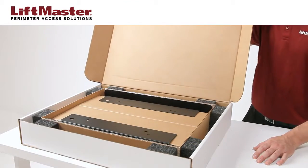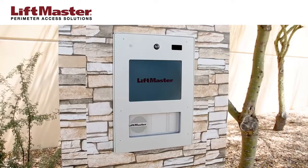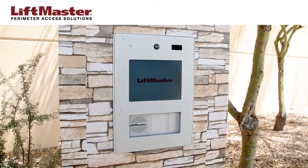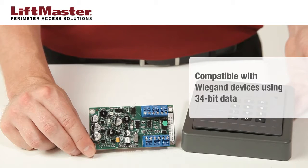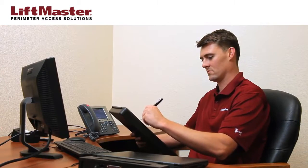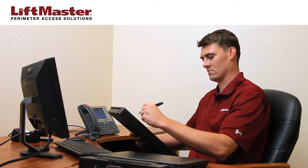If you are replacing an Icon 26 or Infinity L device, you will need to order the retrofit trim ring kit, IPAC RTR. The IPAC is designed to be compatible with a large variety of standard Wiegand, MagStripe, Proximity, Smart Card, and biometric readers. It is compatible with Wiegand devices that transmit up to 34-bit data. You should also make a note of any optional equipment needed for the site, including cameras, protective gear, and passport receivers.